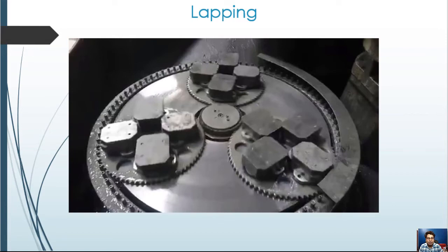Surfaces to be lapped are usually flat. If the workpieces have different geometrical shapes, correspondingly modified methods must be applied. From an economic perspective, these are not always a reasonable choice of application. Given high demands on the quality of the workpiece, however, flat or cylindrical lapping has proved competitive in comparison to ultra precision turning, precision grinding or honing. So they are being employed nowadays. Often it is the only option to achieve the quality requirements needed.